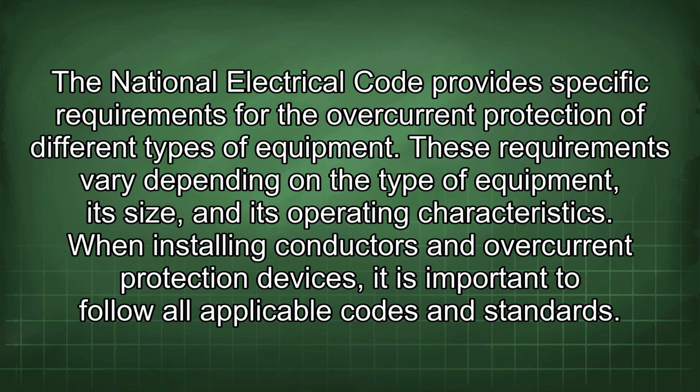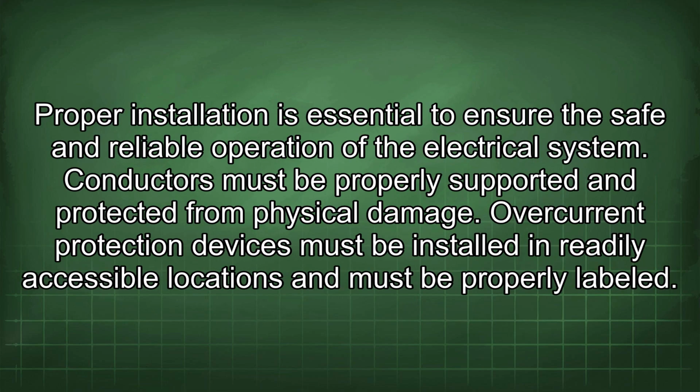When installing conductors and overcurrent protection devices, it is important to follow all applicable codes and standards. Proper installation is essential to ensure the safe and reliable operation of the electrical system. Conductors must be properly supported and protected from physical damage. Overcurrent protection devices must be installed in readily accessible locations and must be properly labeled.